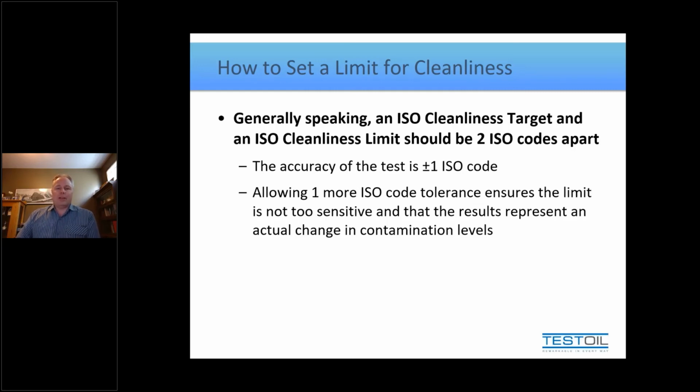So with that, hopefully the big points I've hammered home in this first module of, like I said, a series of 3 are: 1, new oil is not clean oil. It's not clean enough for most systems to meet most OEM recommendations. And 2, how you set that target cleanliness is, if it's not coming straight from your OEM, you can set it yourself knowing where your tightest clearances are located. And if you don't know that off the top of your head, that's what the charts are for. They help you along that path to understand just how clean it should be.